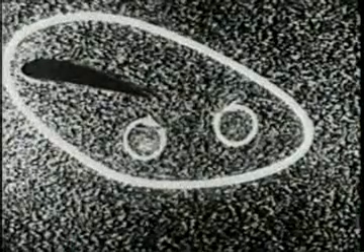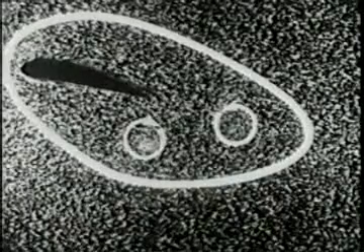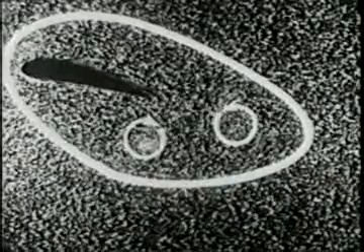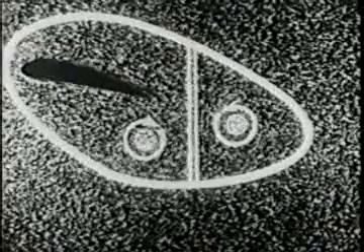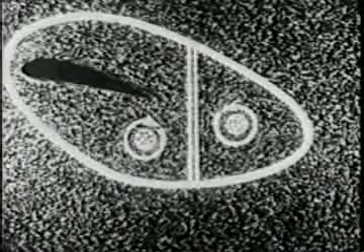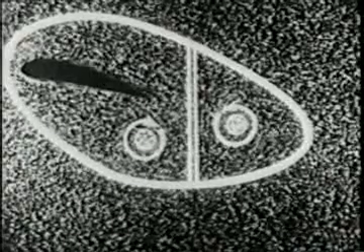Now, when the airfoil stops, the bound vortex is shed as a stopping vortex, again because of viscous forces at the sharp trailing edge. On a circuit around either vortex, viscosity has acted and circulation is present. But on a circuit enclosing both vortices and passing through fluid on which friction has never acted, the circulation remains zero. Thus, the equal and opposite vortices produce zero net flux of vorticity through the entire bounded area.